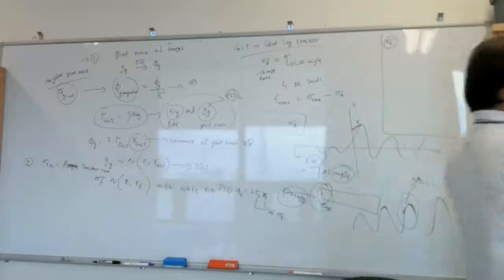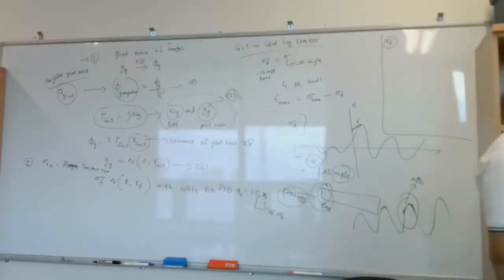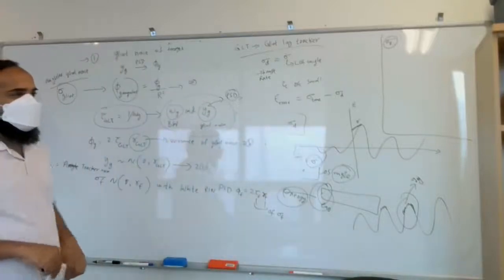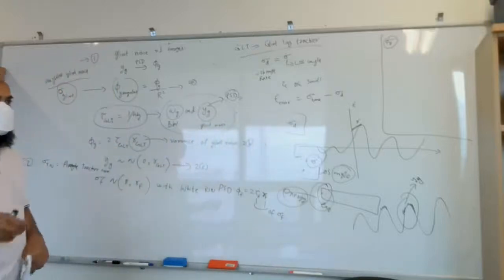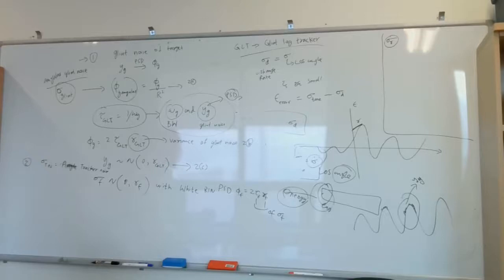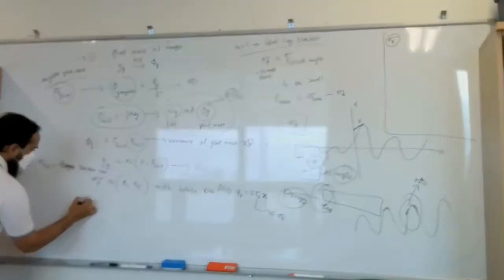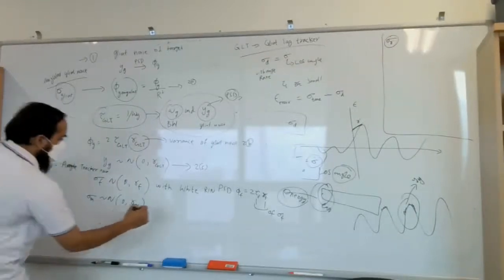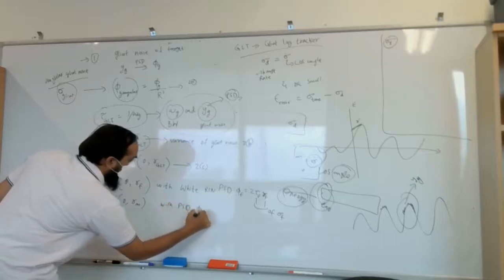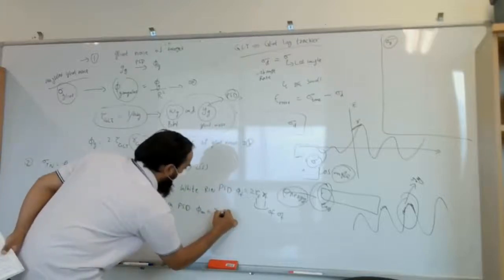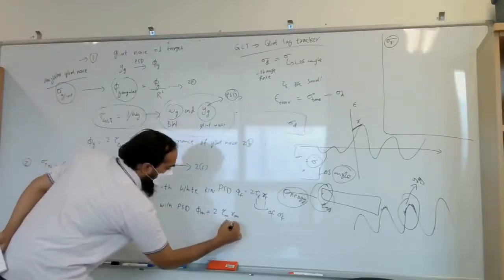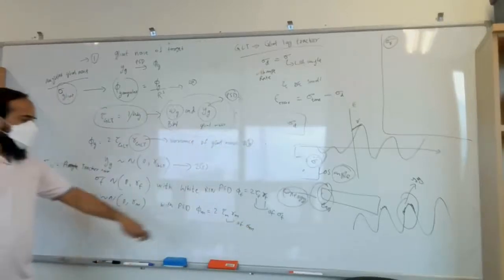Now this is the receiver noise. It is caused by many sources: signal processing effects, cross polarization of the data returns, quantization effects, and gimbal servo drive inaccuracies. Thermal noise is also a receiver noise, which is a function of the target return signal strength and the signal to noise ratio. So thermal noise also has zero mean and variance Rn with PSD. This is the time constant, and this is the variance of the thermal noise angle.